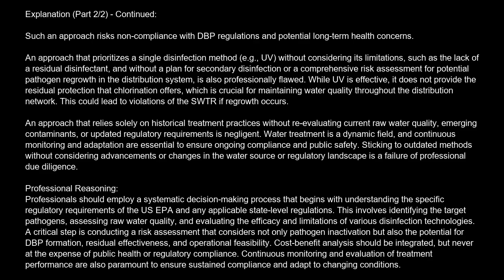A critical step is conducting a risk assessment that considers not only pathogen inactivation, but also the potential for DBP formation, residual effectiveness, and operational feasibility. Cost-benefit analysis should be integrated, but never at the expense of public health or regulatory compliance. Continuous monitoring and evaluation of treatment performance are also paramount to ensure sustained compliance and adapt to changing conditions.